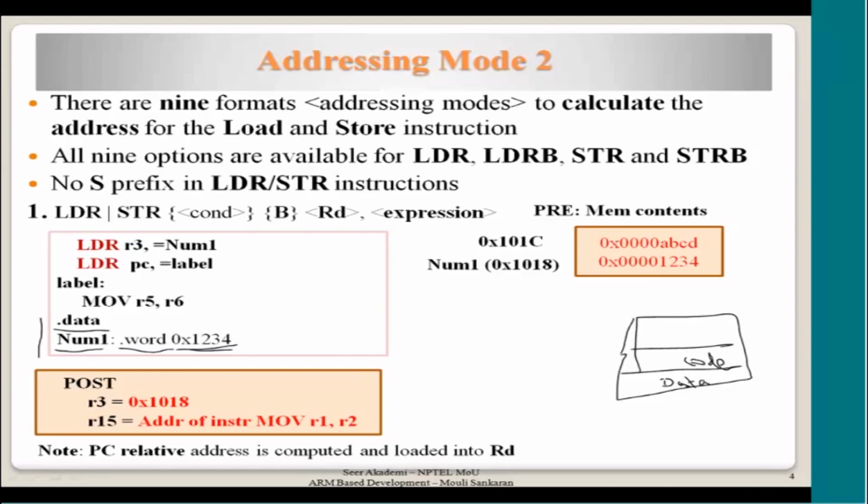The loader, which is taking the assembled output of this file and loading it into the memory. It is actually maintained by the simulator. The ARM simulator that we have assumes the code starts from address 1000 hex. It could be modified, but this is what it assumes.